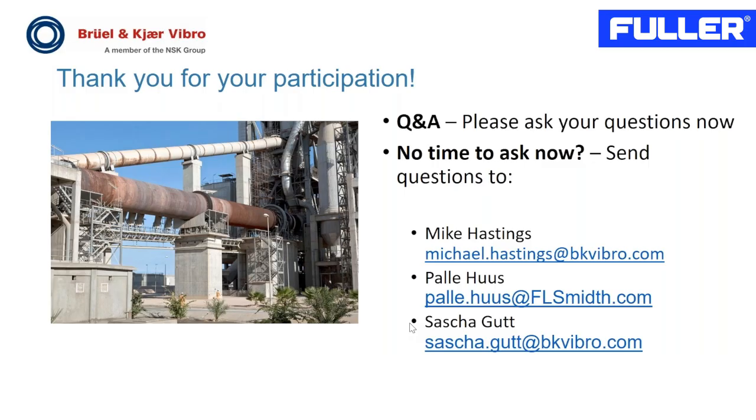Yes, I'm well aware of that system from another supplier to the cement industry, where the intention is to avoid hot spots, hot areas on the kiln shell by spraying on the water. Potentially the solution works. I'll not question that in this session. It is, however, not something that we have decided to implement in FL Smith. Basically, it is a symptom treatment, and we believe in working towards the root cause of the issue.